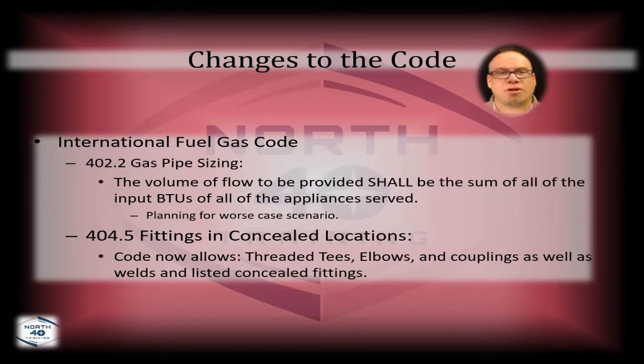Well, because now you go down in Grandma's basement, it's finished. Everything has to be concealed. And there were no allowances or tolerances for concealing those black iron fittings in the past. They had to be accessible. Now, they didn't have to be open, but they had to be accessible. Now, the only things that have to be accessible are serviceable fittings, shutoffs, unions, flares, things like that. They also have the higher leak potentials.